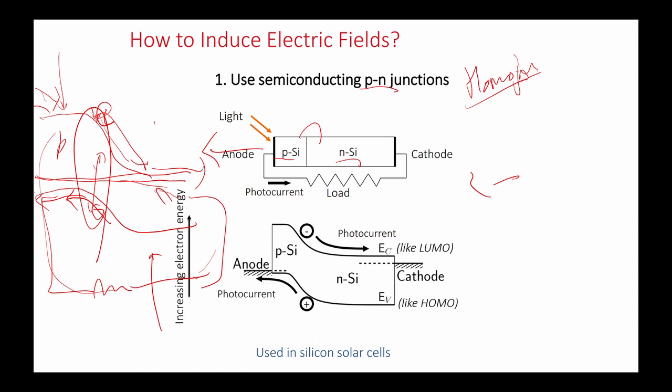If most of the electron hole pairs are generated in this region, which is the P region, they won't be collected because they will recombine here only. We do not want the recombination. We want electrons and holes to be collected at the respective electrodes to give the current. If they recombine, there won't be any current.